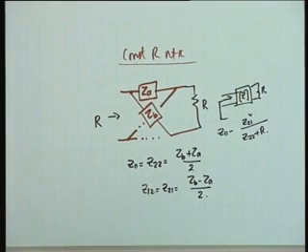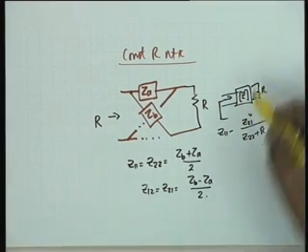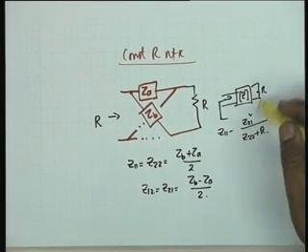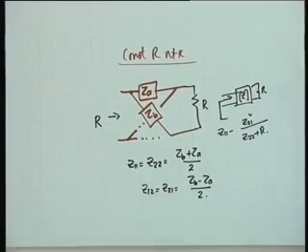Very simple. How do you do that? So T network with Z11 minus Z12. Okay, you can use a T equivalent because of the mathematical equivalence. You are not replacing it by a physical network, and then you can find this out. Or you can go back to the roots. V1 equal to I1 Z11, etc., etc., and then you write V2 is equal to minus I2 R. Okay.